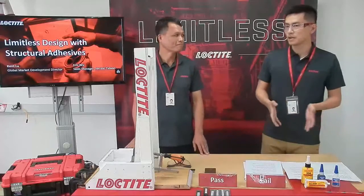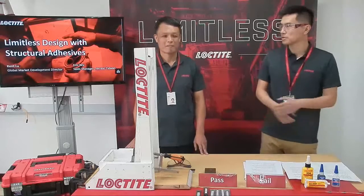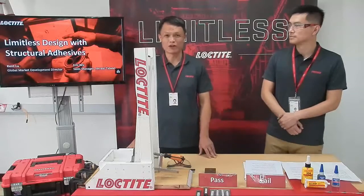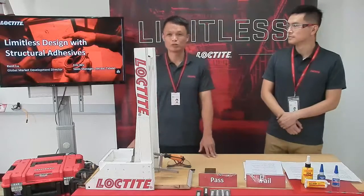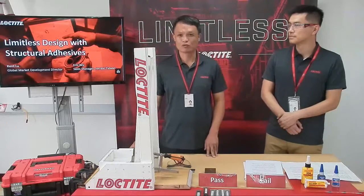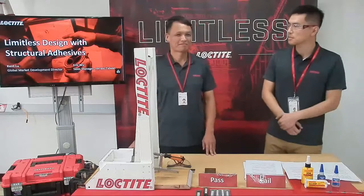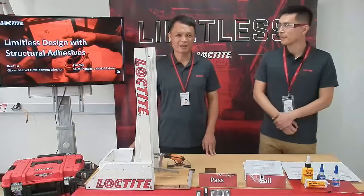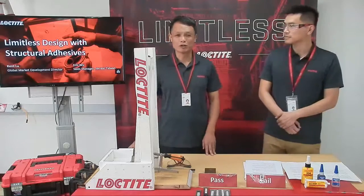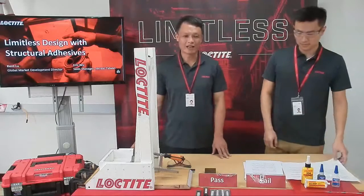Then when designers are designing their products, what are the requirements they think about for structural bonding? For structural bonding, the requirement is not limited to functionality, but also has to be compact, lightweight, and strong enough to withstand the dynamic loading applied. Okay, so which one is the most critical one? I would say dynamic loading. The dynamic loading includes vibration, repeated cycle loading, impact, and so on.